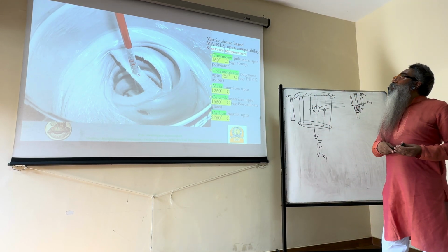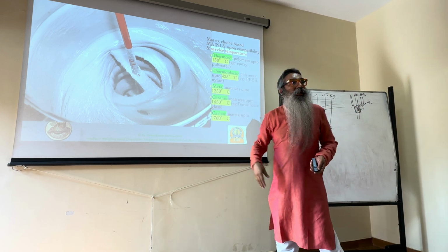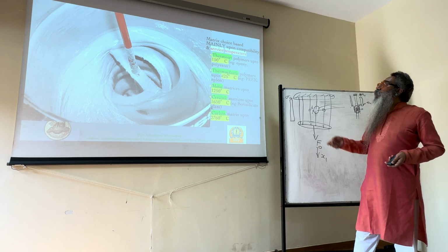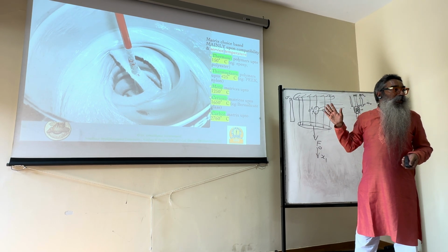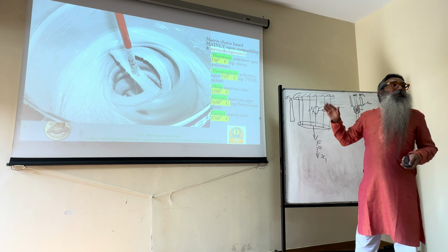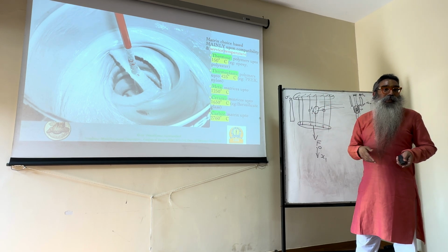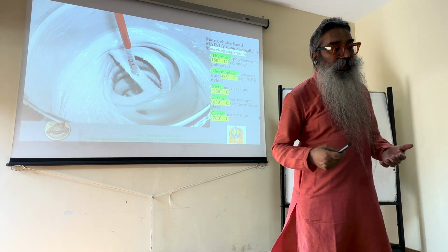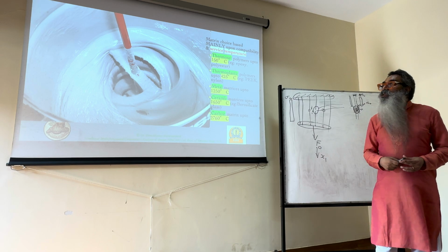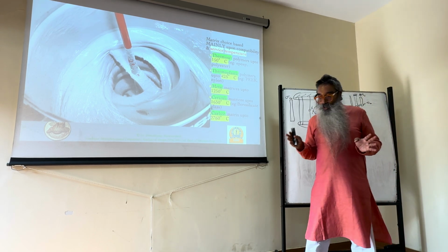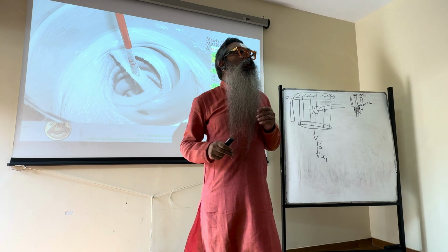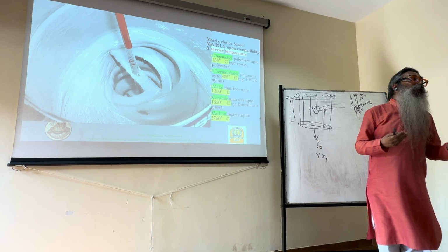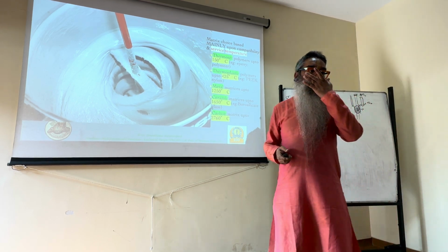So it is very important to remember that yes, there are many functionalities of the matrix, but more or less all matrices will do that for you. The specific choice of matrix has to be based on physical and chemical compatibility with the fiber first of all, and once that is done, purely based on the service temperature, because that determines whether the matrix will survive or not. Once the matrix is gone, the fiber can't do much by itself, as we already saw, and therefore it could be a disaster. Therefore, you have to ensure that you have a very proper understanding of the component that you're designing, not only the mechanical loads that it is going to experience, but also the temperatures and humidity, etc., so that we can take care of all of these.